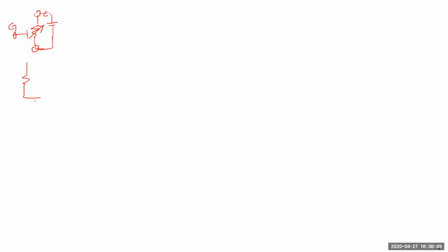So basically, for a gate, let's say this is your load cap. You have two voltage-controlled resistors, one from VDD and one from ground. Whenever we want a one, we make this VG with respect to VDD lower, because it's a PMOS. I think most of you understand now that this resistance becomes lower and it will charge this cap. Otherwise, this resistance will be really, really high, where the current is almost equal to 0. And in the other case, I'll turn this on and this off, right? So that's the whole idea.